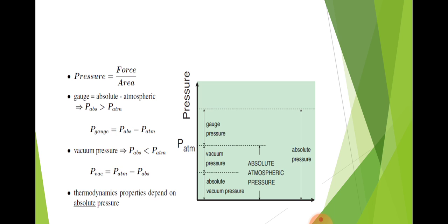Plus the pressure due to the column of mercury at height H. So the actual pressure we can find by the addition of pressure due to atmosphere plus the height of the mercury in that column, and the pressure we get is the absolute pressure of the gas in the vessel or the pipeline, the sum of both readings.